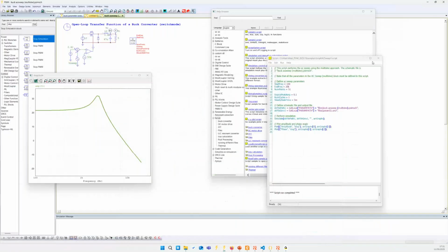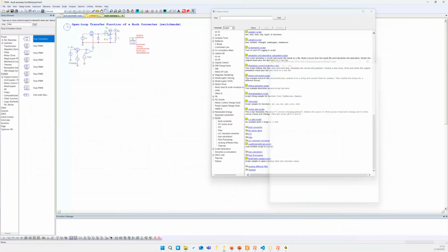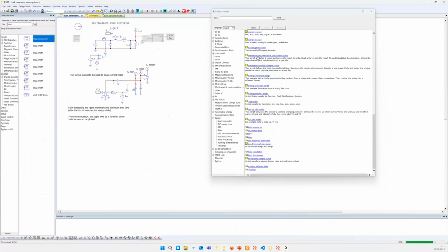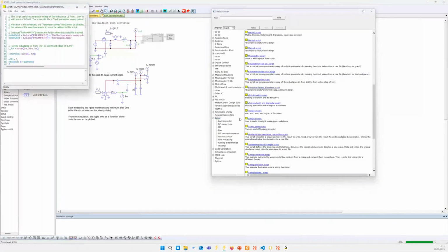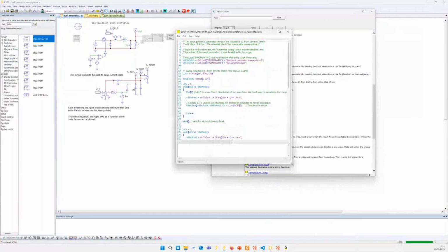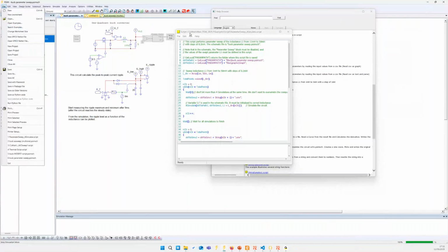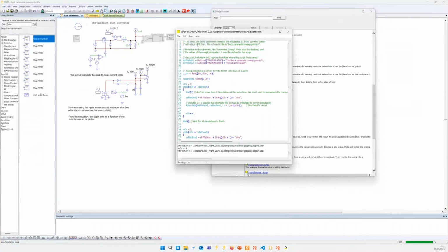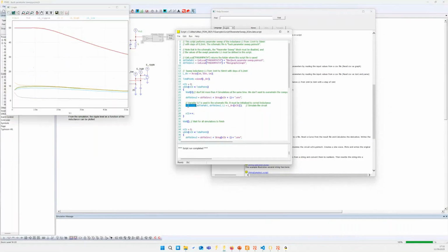So the simulation in play is this one. And the script I'm going to use is the parameter sweep asimulate. This is all of these results. You can directly run them yourself if you navigate to File, Search Examples. So I will click Run Script. And what is different in this case is that instead of using the simulate function, I'm using the asimulate function, which basically means I'm running simulations in parallel in a multi-thread approach this way.